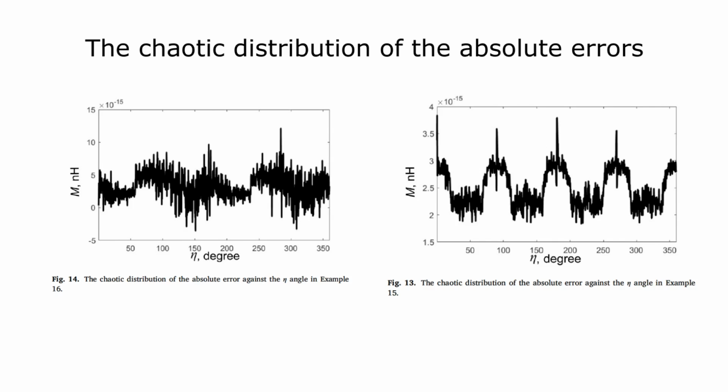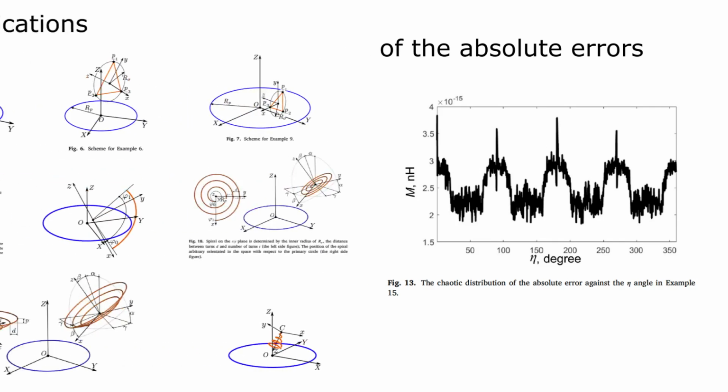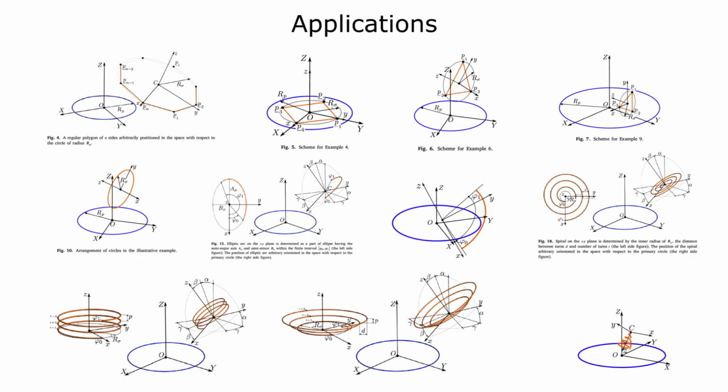They looked at mutual inductance between a circular filament and polygons like squares, triangles, and hexagons, positioned arbitrarily in space. They also tested spirals and helices, which are common in wireless power coils and sensors. And elliptic arcs and ellipses too, right? That really shows the flexibility of the method. Exactly. Basically, any shape that can be represented as a curve in three-dimensional space can be handled.